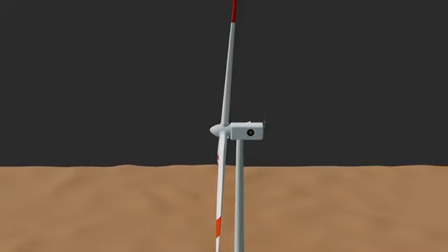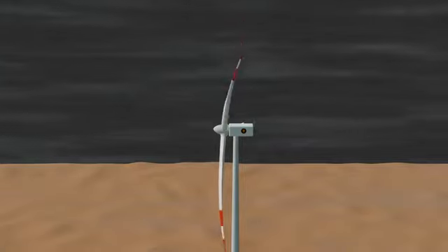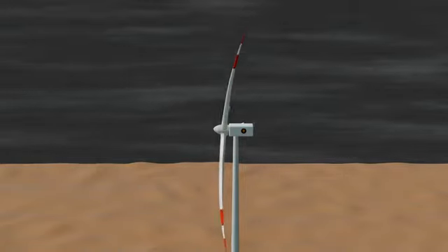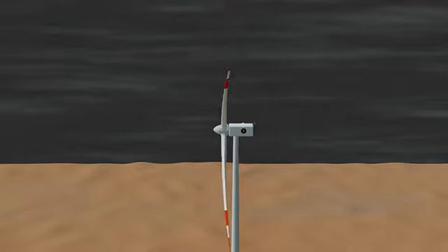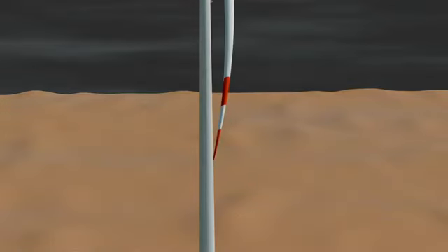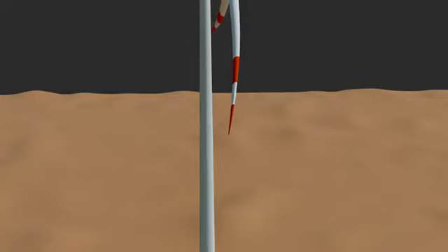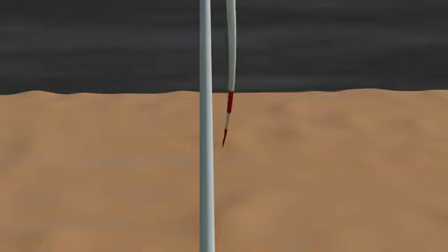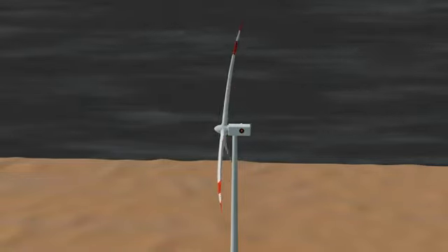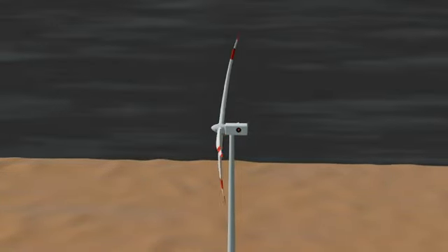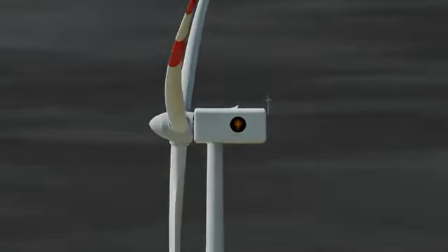Wind turbine blades are not perfectly rigid. They are flexible. Under high wind speeds, the aerodynamic thrust pushes the blades backward, causing them to bend toward the tower. If the rotor is perfectly horizontal, a strong gust could bend the blade tip enough to hit the tower as it passes the lowest point. By tilting the rotor shaft upward, the blades rotate in a plane that leans away from the tower. This increases the distance between the blade tip and the tower wall, known as tower clearance, ensuring that even when the blades flex under maximum load, they remain safe. For a standard 2 megawatt wind turbine, this tilt angle is typically between 4 degrees and 6 degrees.